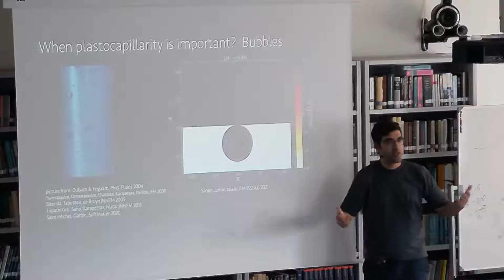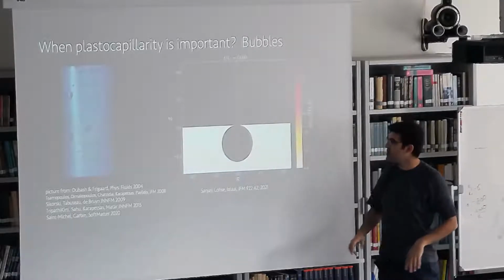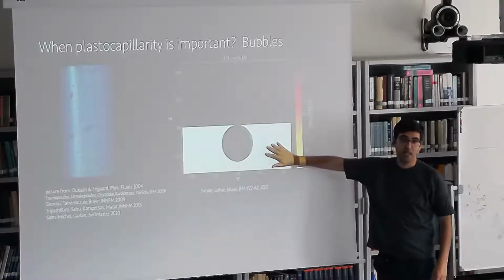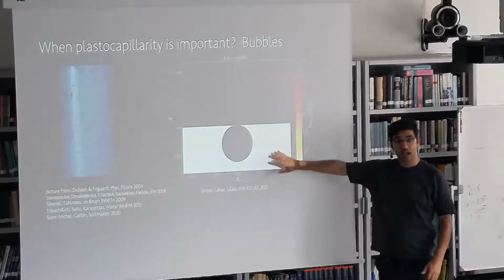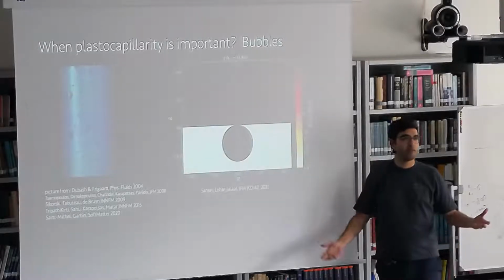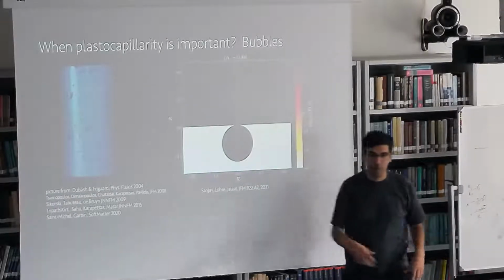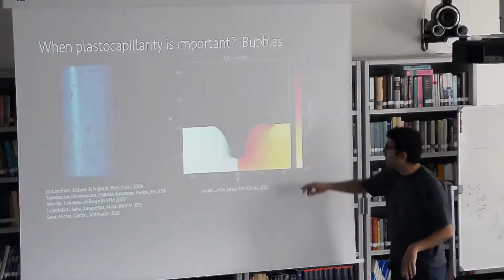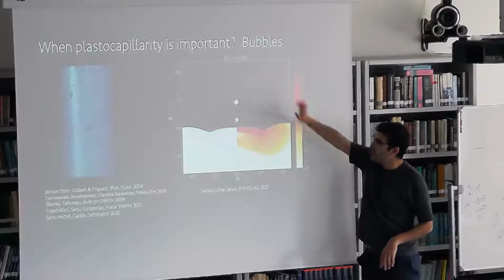For a Newtonian fluid, it is very well known, and there's a lot of complexity already in the Newtonian case. We thought, let's make it more complicated, and we make this liquid viscoplastic. So we added yield stress, and there's no gravity here, so it's a pure plastocapillarity problem. Surface tension wants to minimize the surface and collapse the bubble, and yield stress in the bulk is resisting it. The color you can look at as a deformation. You get these Worthington jets and the bubble and everything.